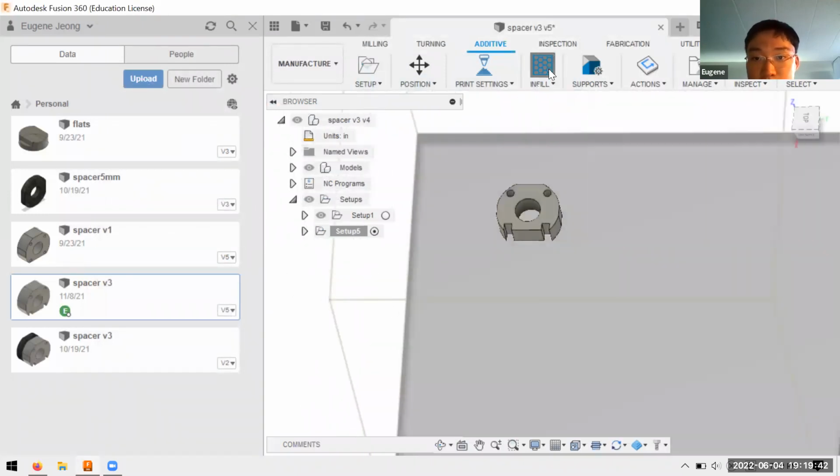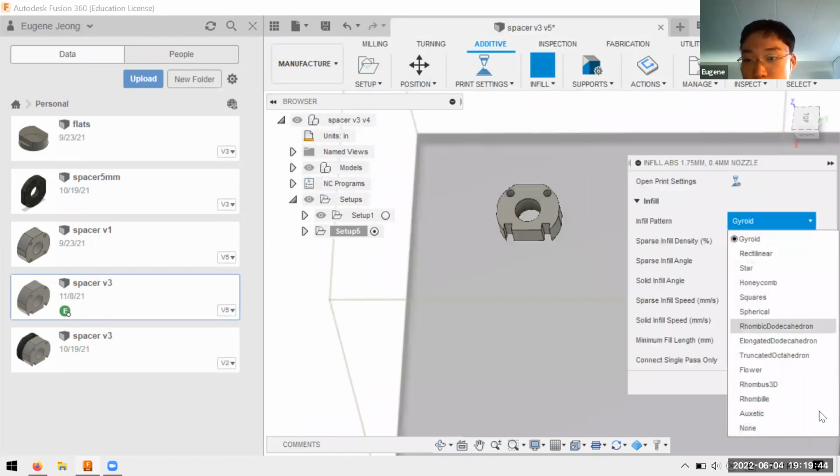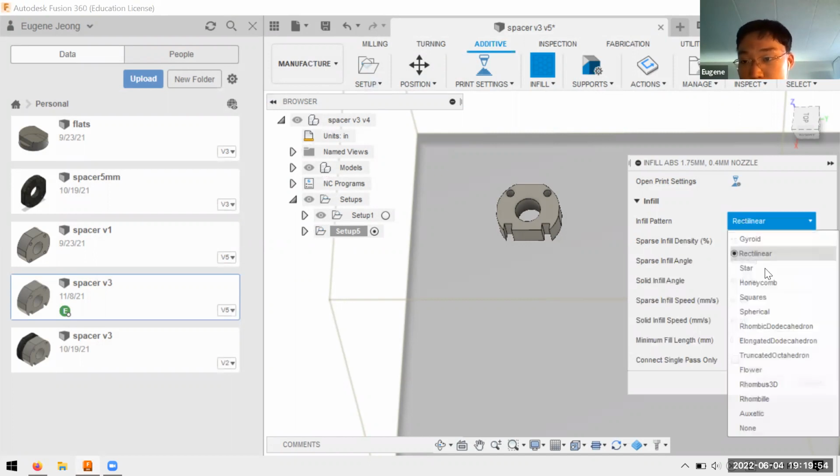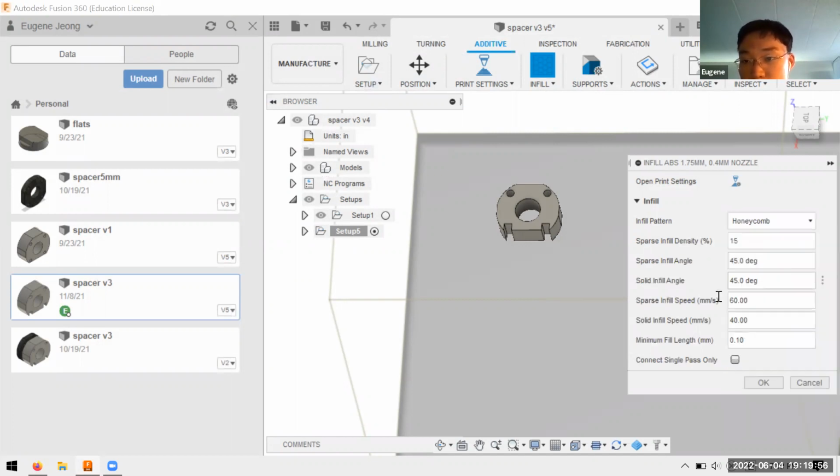Infill is something we talked about. So you can say what kind of pattern you want the program to use in filling the shape. I can specify how densely filled the part should be, the raster angles, things like that.